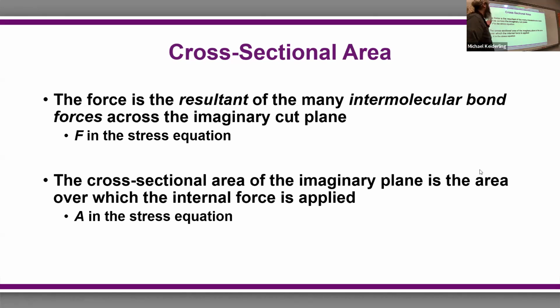So the force is the result of many intermolecular bond forces across that whole imaginary cut plane. That's the force. And the cross-sectional area of the imaginary plane is the area over which the internal force is applied. That's the A, the area in the stress equation. So that's stress. It's written with lowercase sigma.